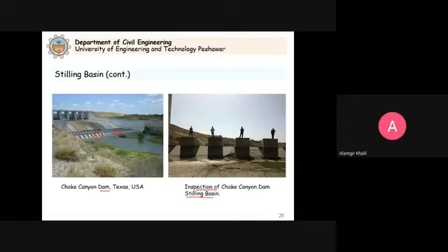So the idea here is, this is for the stilling basin, and the idea is to initiate the hydraulic jump and contain the hydraulic jump so as to protect the channel bed against erosion, and also it will increase the stability of the hydraulic structure because it will reduce any threat that can develop. Clear? So we can study in detail the design of stilling basins when we have a course on hydraulic structures. Clear? So this was just a brief introduction about the stilling basin, the purpose.